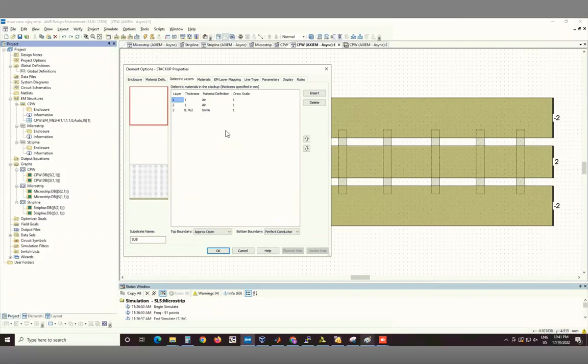But maybe given the dimensions here, this is a 50 micron gap, right? No, sorry, 100 micron gap. And this is 500. But my air block was 1 millimeter, the virtual boundary. So it's 1 millimeter up, about 500 microns across, and 1 millimeter down. So it's actually a very long path, 2.5 millimeters for this kind of thing. Maybe it's too big, too inductive.